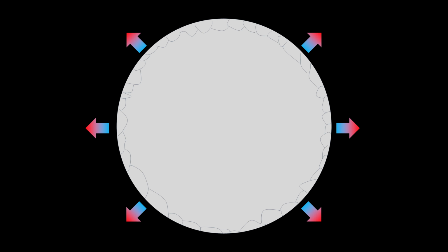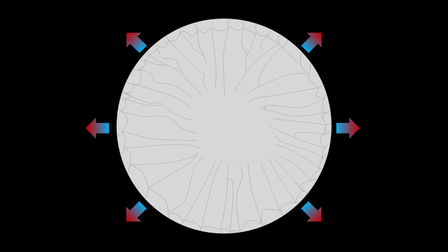With sufficient nucleants and the right solidification conditions, a Columnar-to-Equiaxed transition can occur in a solidifying alloy. We see this in castings very often, where the alloy solidifies as a single crystal structure off the crucible. The individual crystal grains grow inwards along the thermal gradient without any further grain nucleation, with each single crystal growing as a single structure towards the centre as columns. However, the solute bow wave in front of each forming crystal grows large enough to produce a columnar-to-equiaxed transition, and the structure changes from columnar to equiaxed grains.